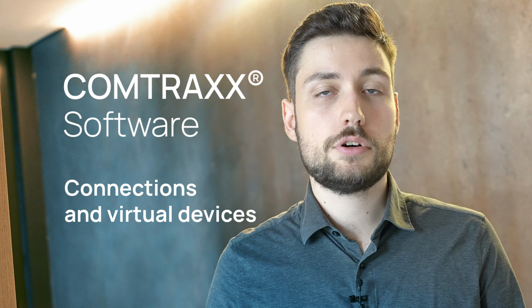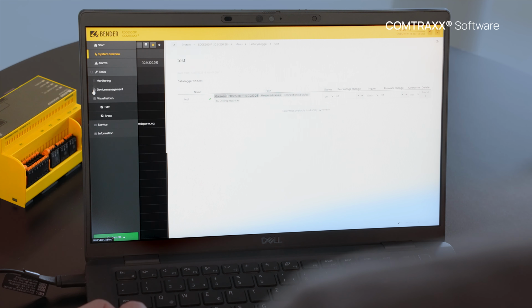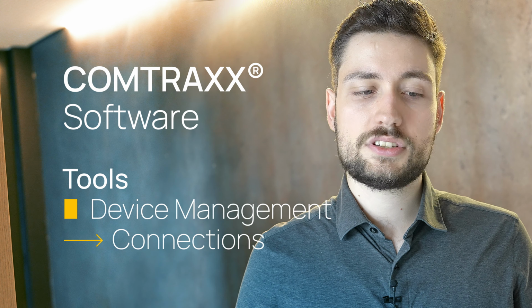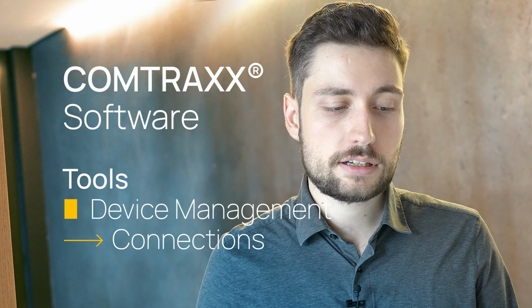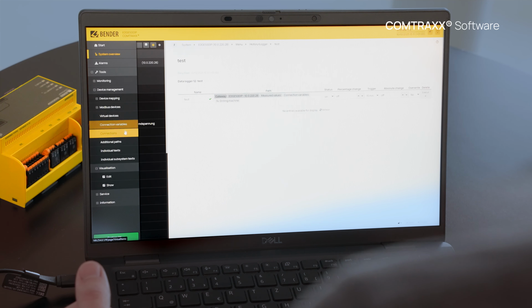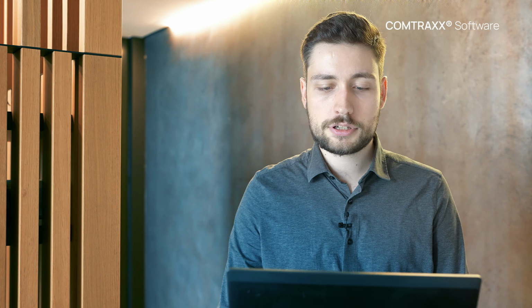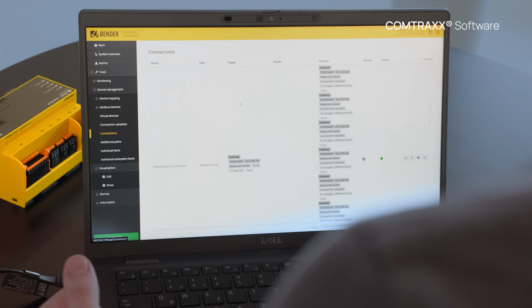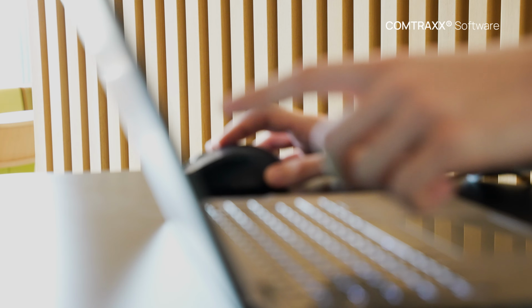Next thing, I would like to show you what we can do with connections and virtual devices. So for this, we go into our Tools menu here, and in the Device Management section, we see virtual devices, connections, and connection variables. Especially connections and connection variables are very important to do what we previously saw in the visualization. So for example, in our connections, we can go here to this error simulation or this fault simulation that we previously set up.